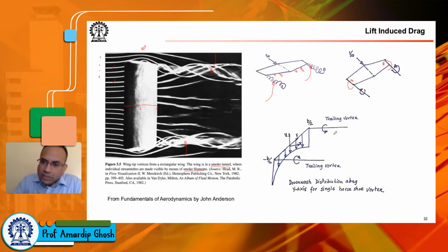Okay, so as I also mentioned, here we are modeling this wing by these horseshoe vortices. You see that when you have these trailing vortices, as you see on both sides, it can be modeled by a vortex tube or a vortex filament with a circulation same as the circulation generated by these trailing vortices. If you look at the wing from a location behind the wing, looking towards it, you will see that the circulation developed by these trailing vortices is something like this. So instead of dealing with the counter rotating vortex trails, you can model it by these vortex tubes.